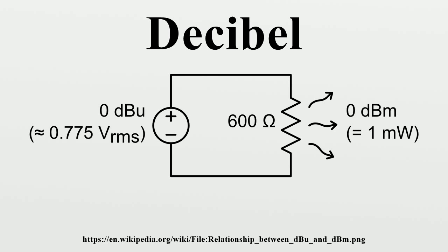Most commonly, quantities called dynamic range or signal-to-noise would be specified in 20 log dBs. But in related contexts the term should be interpreted cautiously, as confusion of the two units can result in very large misunderstandings of the value. Photographers typically use an alternative base 2 log unit, the f-stop, to describe light intensity or dynamic range.